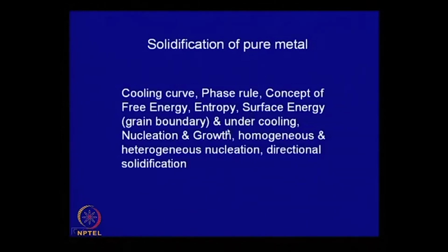We will also explain why for solidification to proceed some amount of undercooling is necessary, and the process of solidification is a time dependent process. There are two steps and these are called nucleation, when a certain number of very small nuclei of solid will form in the liquid.